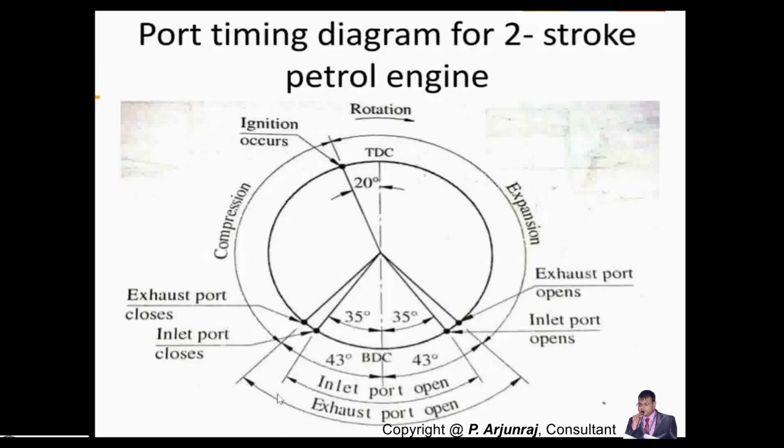And you also have a system of such a way. You see here the inlet opening, inlet closing, inlet port. So here is basically the port. Inlet port opens and inlet port closes. You see the inlet port opens 35 degrees before bottom dead center, and again it closes 35 degrees after bottom dead center. And so this is where the first level of stroke is going to get over.